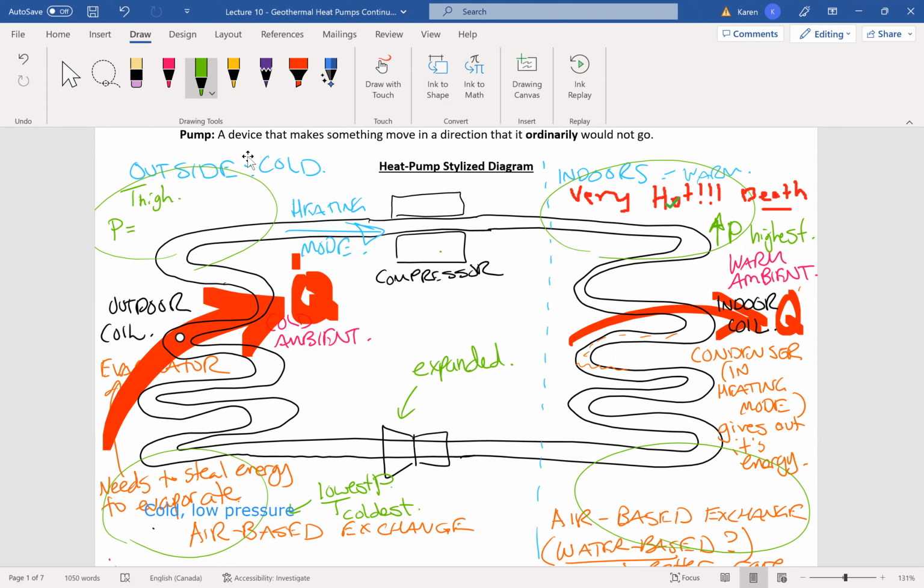That would still be the low pressure, right? Exactly. And why is that? Why is the pressure still the same low pressure? Oh, Jack's beating me. I think this is basically just one tube, right? Like there's nothing exactly in between, so the pressure is going to be the same everywhere. Yes, you were listening in HVAC class last semester. This is just a tube. There's no compression, there's no expansion, so it's just that same low pressure.